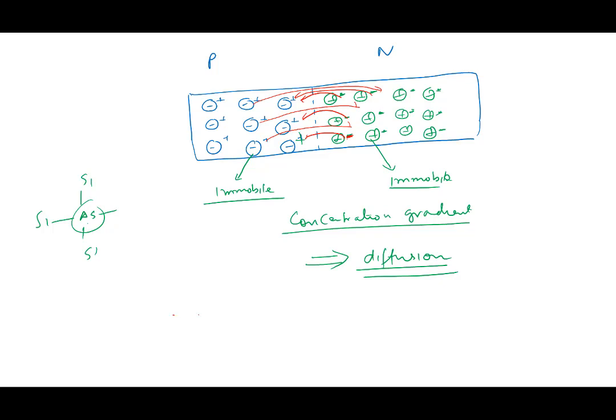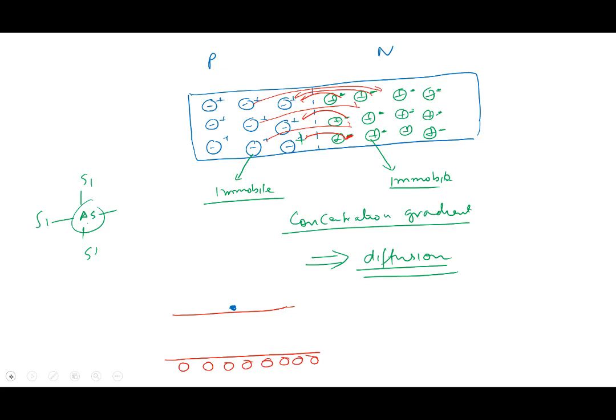So remember we said you look upon a semiconductor like this here. So if I take this electron, and it has come to the p-type, in p-type what do you see? A lot of holes, empty states, right? A lot of empty states in the p-type. And this electron happened to come here to the p-type, diffuse. What will happen immediately to it? It finds a hole and drops into it.